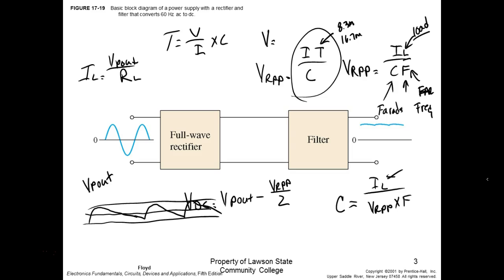So this gets us through filters, right? So basically, this is just a rule of thumb. If you come over here and measure this RMS value coming into the transformer, and you convert that to DC, what you can see is your average voltage should be slightly less than just VP. A real fast troubleshoot, right? We know it's going to be less because we didn't account for the rectifier drop, right? And we didn't calculate the V ripple DC. Well, we should have a pretty good idea of what our output is going to be, just by taking my meter and measuring.